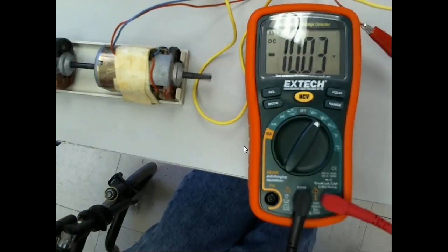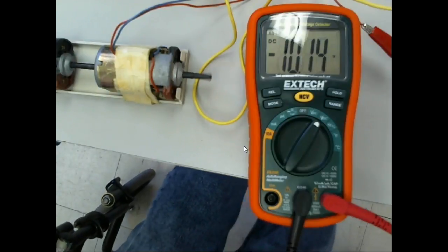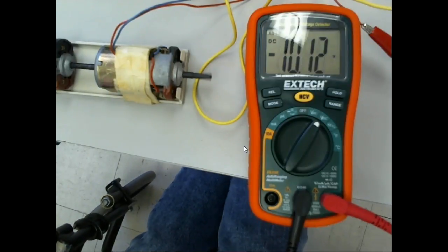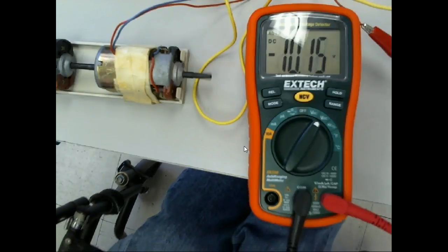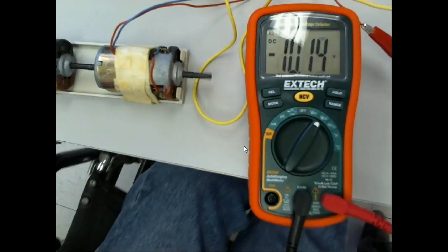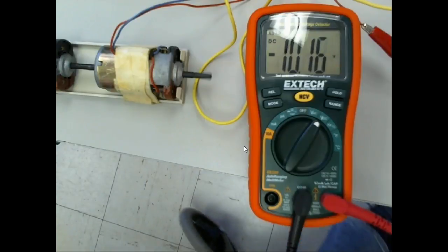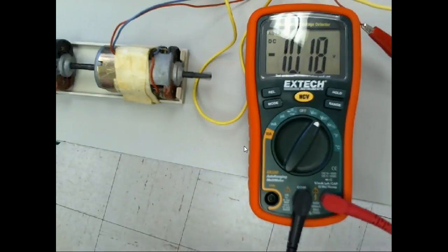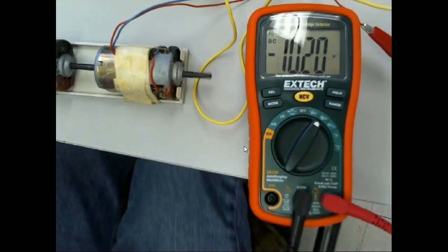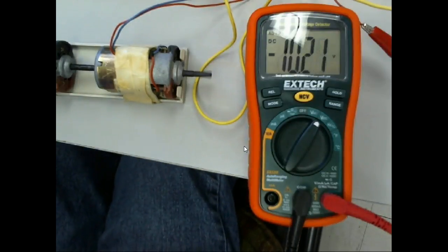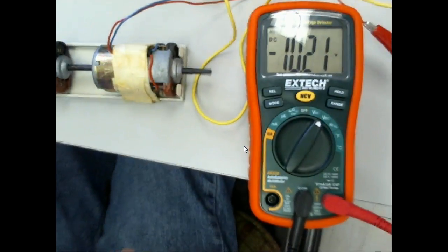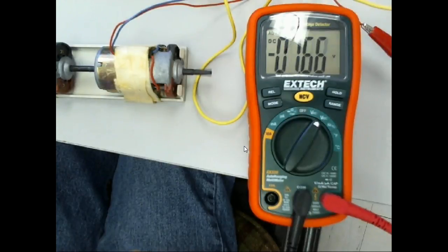If I can measure the speed of the motor when my tach generator was putting out that voltage, then we can make that voltage relative to speed. So I'd have to have some means to measure the actual speed. That's about 10 volts out of the generator when it's running at almost 15. And this is directly proportional. It is really linear.